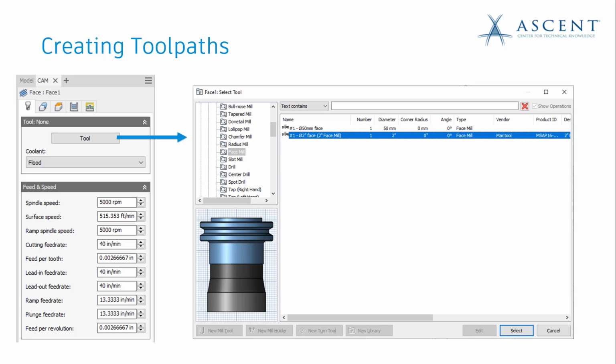Whether you're creating 2D or 3D milling or even drilling toolpaths, the toolpath palette is always used. The options and parameters that will be presented on this toolpath are all based on the type of operation and toolpath that you're actually selecting. The key thing here to keep in mind is the interface. So what you really want to focus on is that. In general, the first toolpath that you would be looking to create in most of your models will be a facing sequence. So I simply chose this as my example to show you the overall palette, how the tabs look, that type of thing.